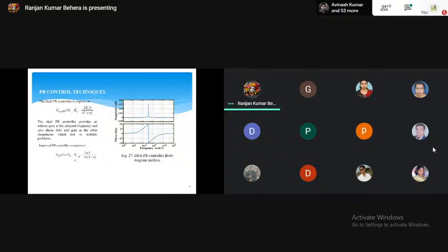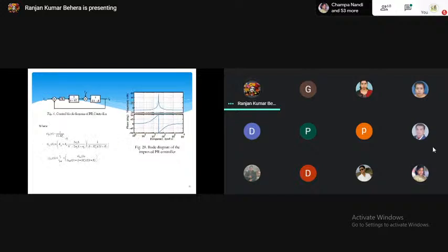Why we use this one? Because our references are DC. When you have an AC reference, what will you use? You need to design a resonant controller, which will take care of the little variation in AC, the AC ripple or the tracking errors. There you can pass and find out what your frequency is, and then you design the parameters.